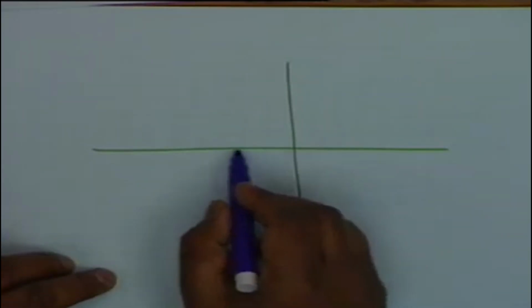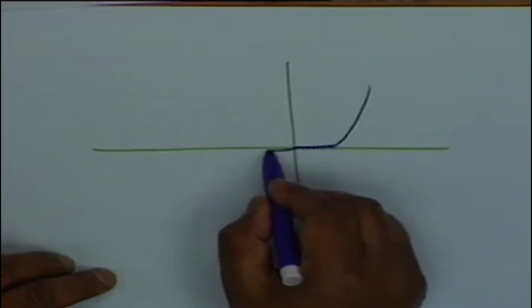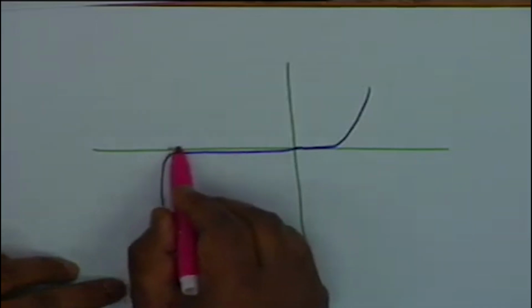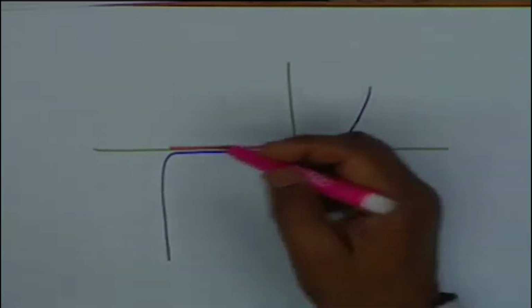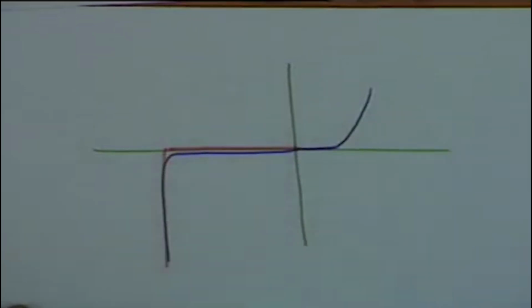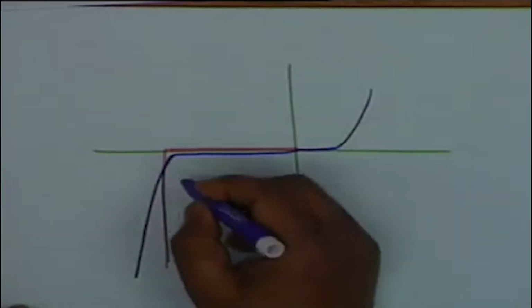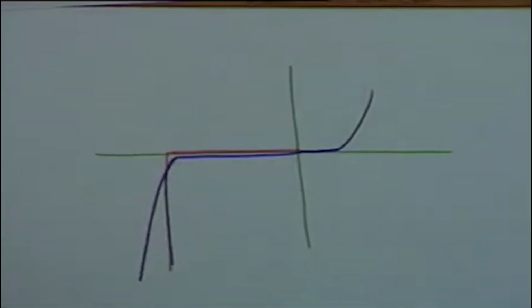A Zener diode is operated in the reverse biasing condition, and one of the models that one uses is this: one approximates this by means of zero current, I is put equal to 0, and then a vertical line like this. I must tell you that the actual characteristic is like this, not a vertical line. This is the actual characteristic. It has a finite slope.